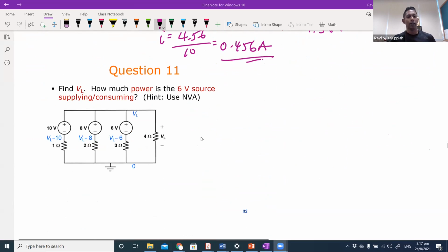Only difference is the placement of the resistor, which in this case is placed sort of behind the supply. Whether the resistor is placed behind the supply or after the supply, at the end of the day, the current flowing in that branch is going to be the same. That means this branch current is the same regardless of whether the 1 ohm is here or here or here, because all of this is considered the same branch.